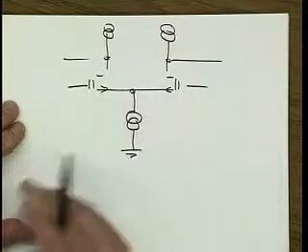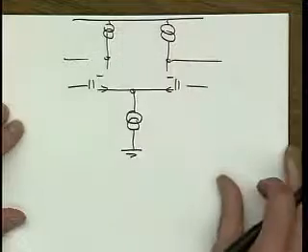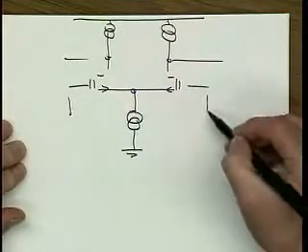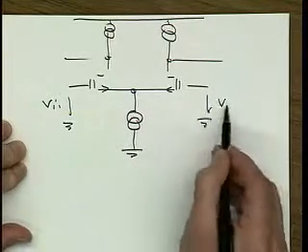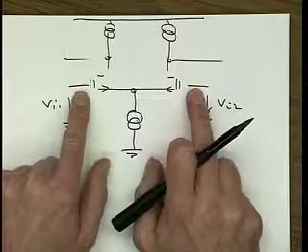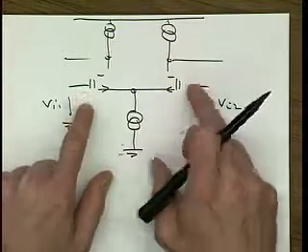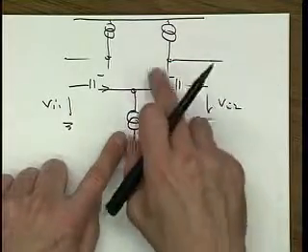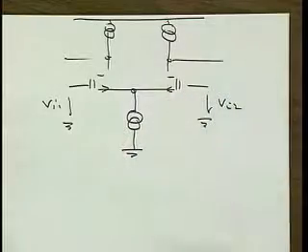I know there should be a common mode feedback circuit. I just do not show it. And I just say this only for those who otherwise will accuse me of drawing things that don't work. So there are two inputs. Now, the actual DC level of these inputs is something, and it can't be 0, it has to be somewhere enough to keep this current source operating, and then the threshold voltage and the V star and so on of this device, like the VGS of this device.